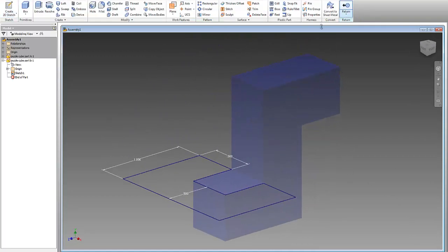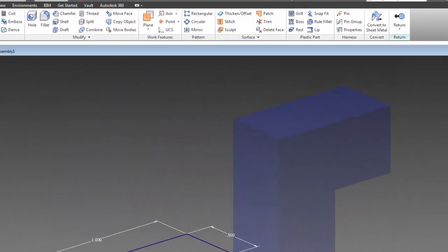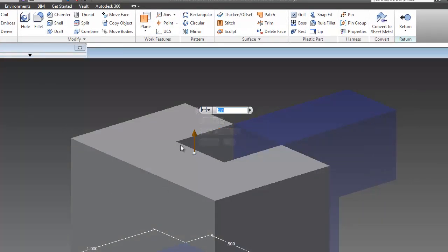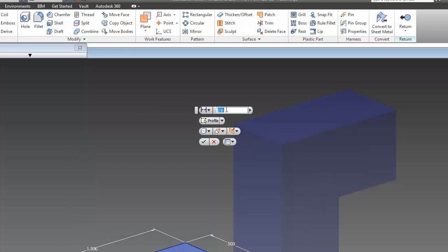So I can now extrude this, and we'll choose extrude. And do I really want to go in this direction? Probably not. Let's go ahead and change the direction to direction number 2. And the distance, remember that D0 was 0.5? I can say I want to make this equal to D0. So whatever that dimension value is, this one right here, this 0.5, if this one changes from 0.5 to 0.75 or to 1, it will automatically update the thickness to be equal to that particular value.